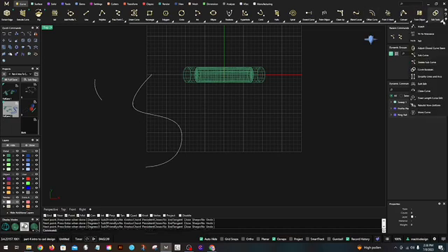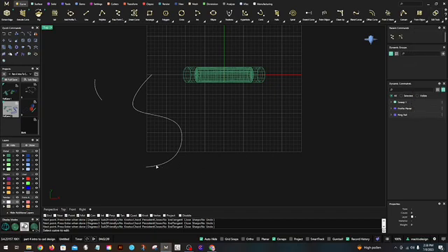And the next one is delete subcurve. So this is really similar. You select delete subcurve, go down to your command line, and it says select curve to edit. We want to select this curve, and you're going to set the point for deletion. So I want the deletion to start here and end here, and do it again. I want it to start here and end here.